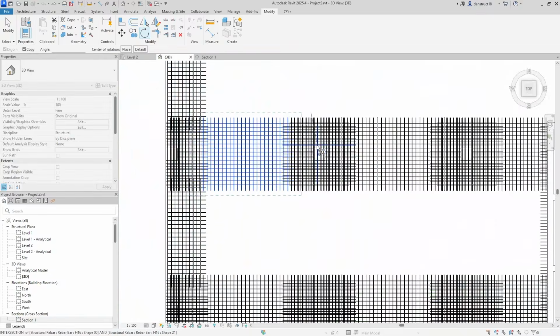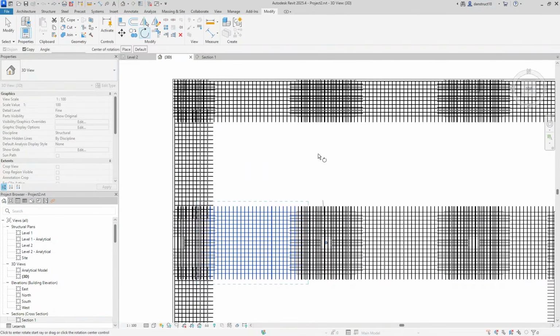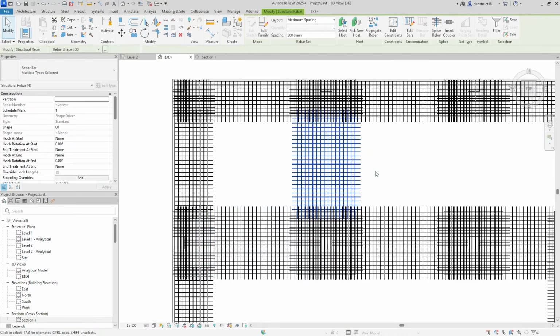I'll click here and I'll form a straight line like this. So make sure it snaps to a straight line, and you want to make sure that copy is turned on. So I'll snap to the straight line, click, move in this direction, and then type in here 90 degrees and press enter. All right, good.